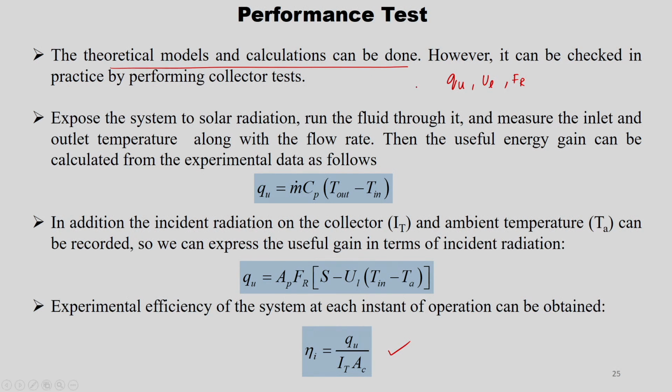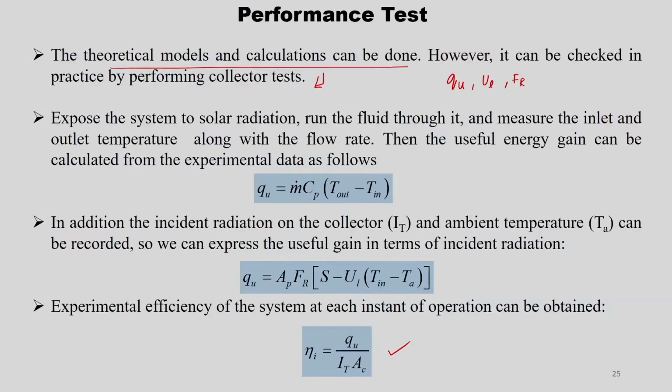However, it can be checked in practice by performing a collector test. Whatever numerical modeling and simulation you do has to be finally validated with experimental results. Or if you are designing a new collector, that test has to be performed to compare with the existing collectors and see how much performance improvement you are able to bring in the new system. For that, you expose the system to solar radiation, run the fluid through it, and measure the inlet and outlet temperature along with the flow rate.